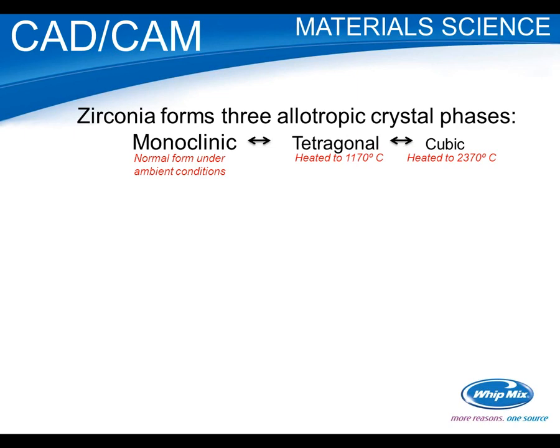And basically, the atoms are realigning and kind of scrunching in a little tighter. So when it's heated above 1170, we have this tighter configuration. I don't know if it's obvious to you, but if you notice my font size from monoclinic to tetragonal to cubic gets smaller. So as it's heated and takes on this other structural form, it's really shrinking in size, getting denser. And then if you heat it further, you'll get to the cubic. That would be what we consider the cubic zirconia.